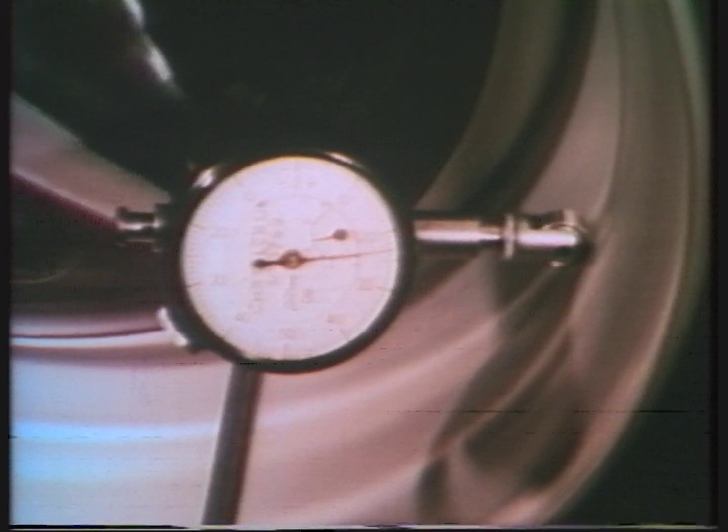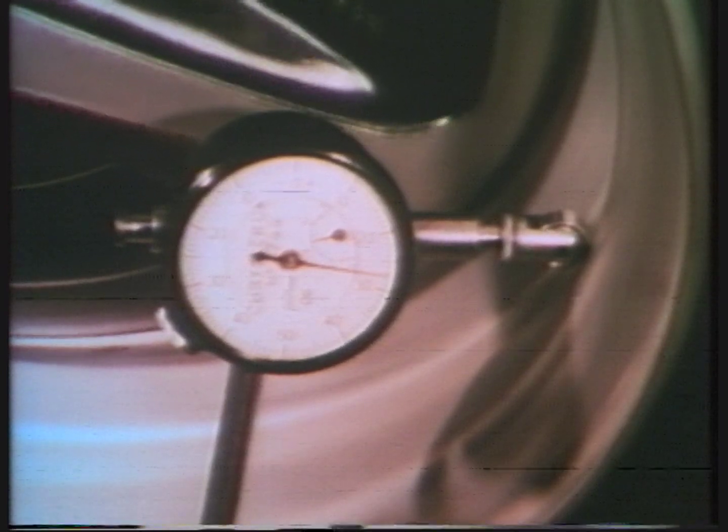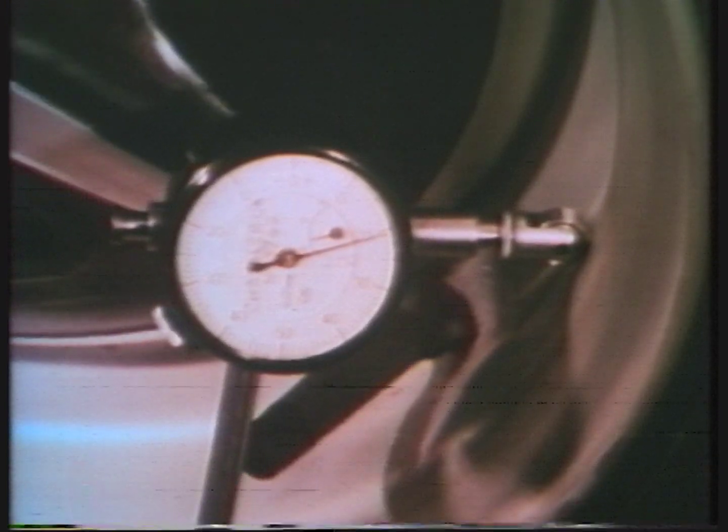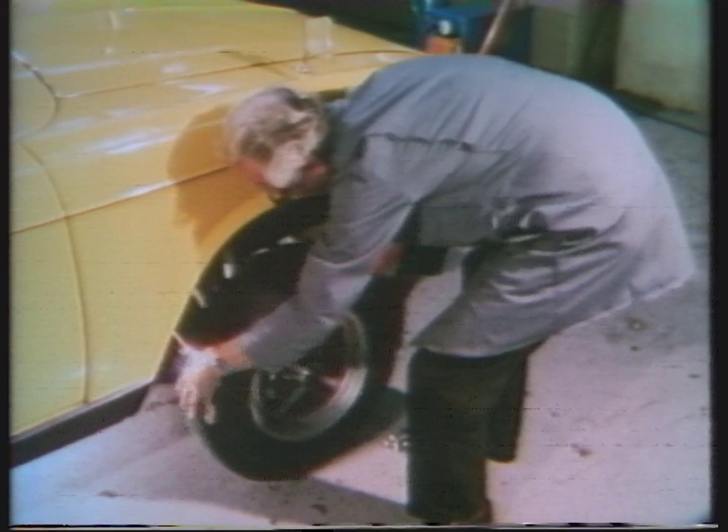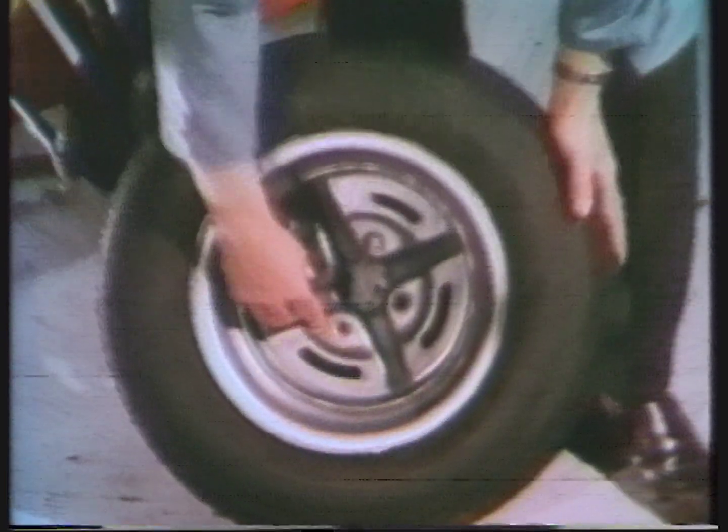Check radial and lateral runouts of the wheel on the hub, placing the clock stylus in the position shown. If the wheel runout is within limits, but the tire runout is not, mark the high point on the tire and the low point on the wheel, and reposition the tire so that the 2 points coincide, and recheck runout.